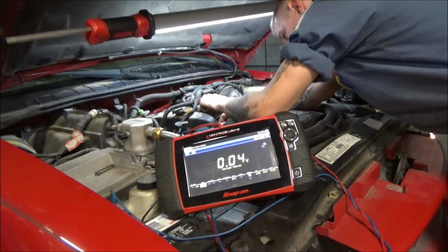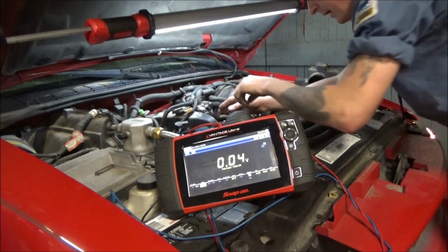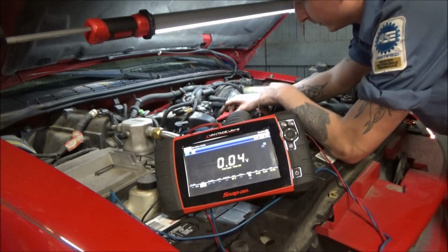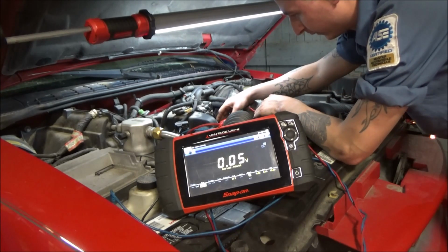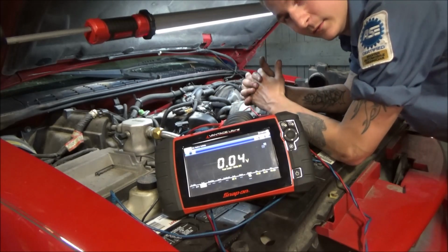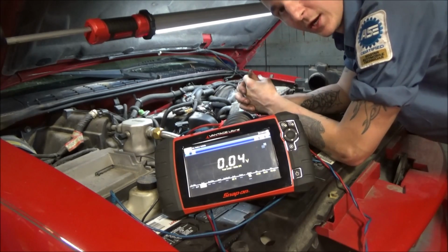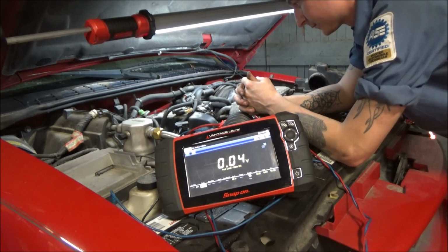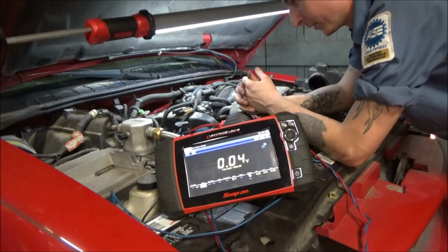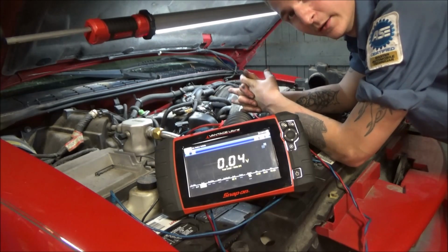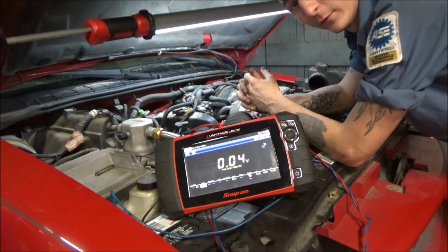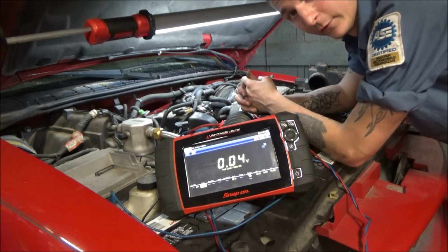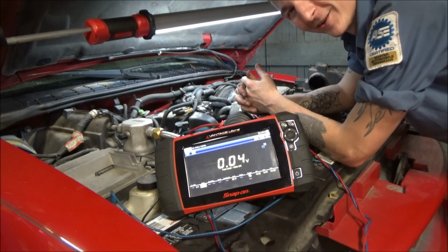And honestly, guys, a lot of guys would just put a throttle position sensor in this car, and in most cases they would probably fix it. But the big thing that I want to stress to you, especially on this channel, is we want to be 100% about the tests that we're doing. Really, I just want to stress being 100% on any call that you make. So we're going to do our diligence, and we're going to test all 3 of these circuits, and make sure that this is in fact a throttle position sensor. I'd hate to be wrong about a call like that.